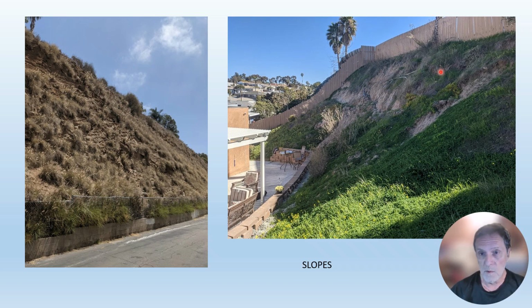It was too steep. It was cut in sandstone with low cohesion, so it's sloughing and sliding as it gets wet. It probably should be laid back or removed and rebuilt as a slope with possibly a higher retaining wall.